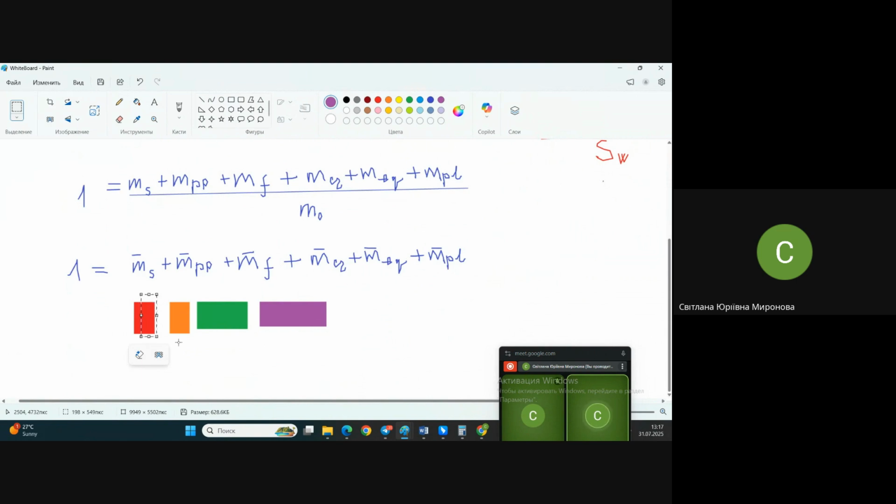But it appears that maybe you increase the weight anyway, because as you reduce the area of wing, the specific load on the wing is greater, and it means that you need to provide a stronger wing. As I already said, it's not a direct decision, it doesn't work so immediately.